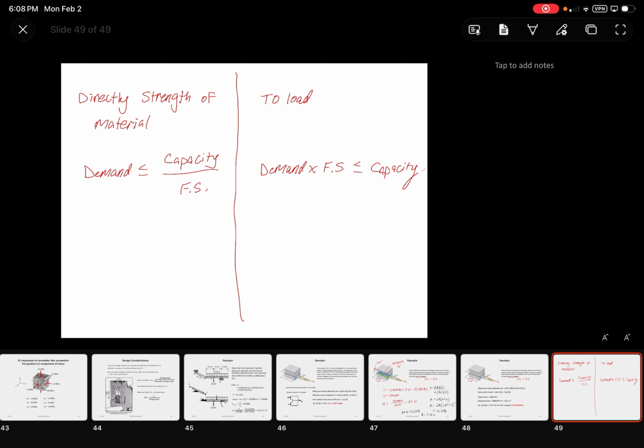All right. And then obviously the factors of safety, those are generally a code requirement. For example, I've designed elevator equipment for certain tunnel projects, and certain elevators actually require a factor of safety of 10 because they're that critical. So you might have a weighted capacity of an elevator of 3,000 pounds, and you're designing it for 30,000 pounds because you do not want those cables to crap out while somebody's in it.